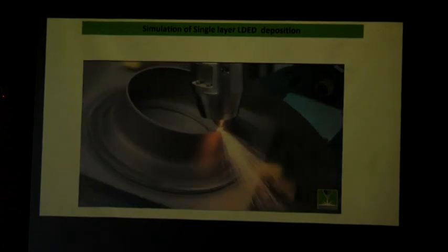With respect to that, we can correlate how much heat has to be supplied to melt the required amount of powder, and to control the solidification. That will help minimize deformation of the components, as well as delamination, and minimize the residual stress also.